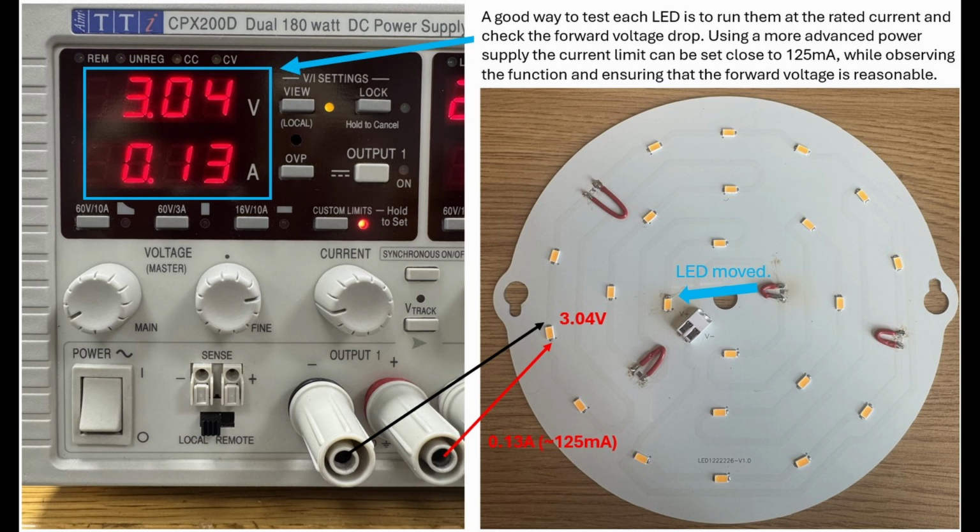Going through all the LEDs, most gave a voltage drop of about 3 volts at about 125 milliamp, but some did not. On one side I had 3 damaged LEDs. One of them was an open LED I had already removed, but I had 2 additional LEDs on that leg with voltage drops of 4 or even 5 volts.